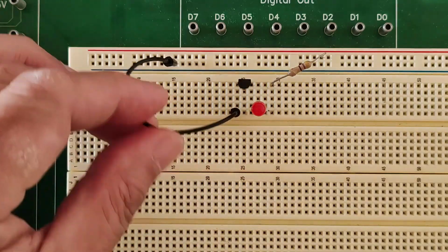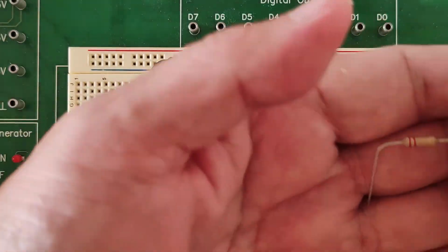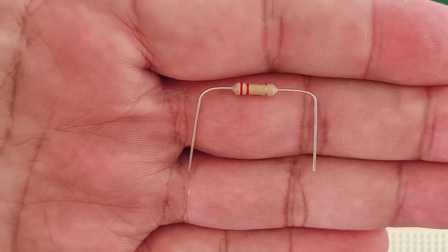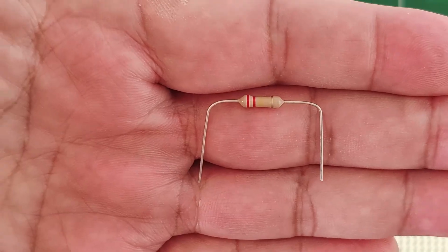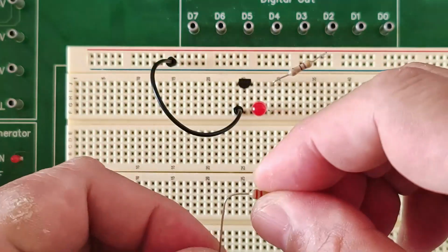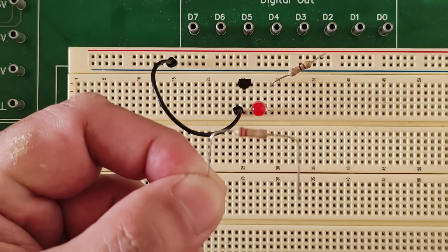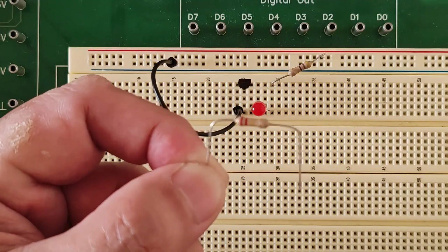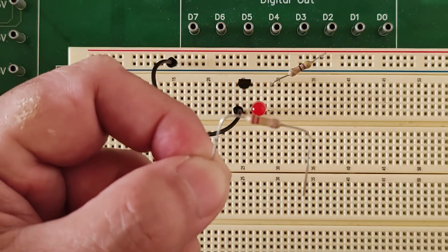Okay, now, the base is connected to a 220 kilo ohm resistor. I have that here, 220 kilo ohms. How do I know again? Again, color code. Check the colors on the body. Now, the 220 kilo ohm resistor is connected with one leg to the base, and the other leg will be connected to the positive terminal of our function generator.